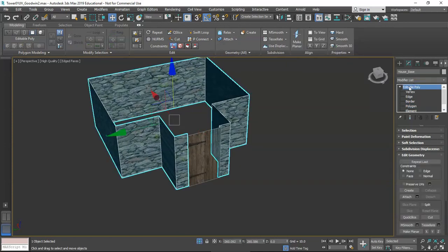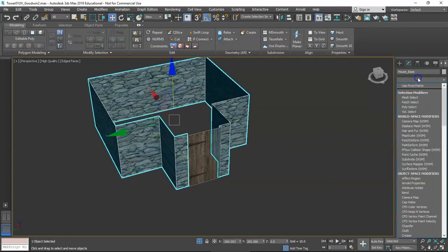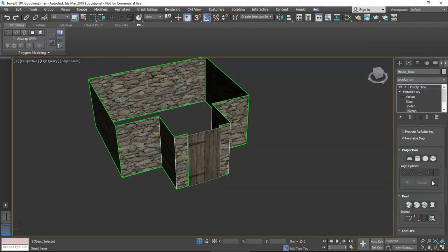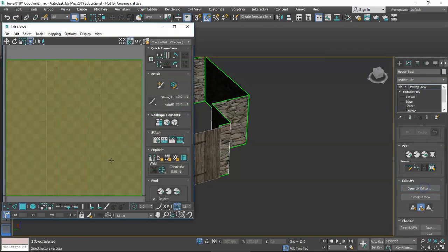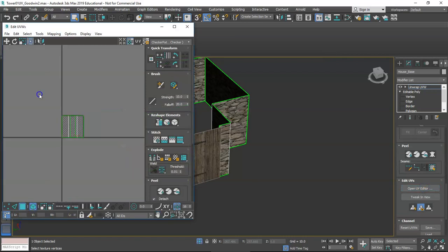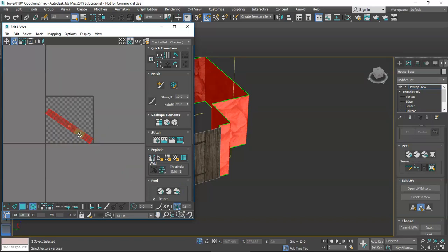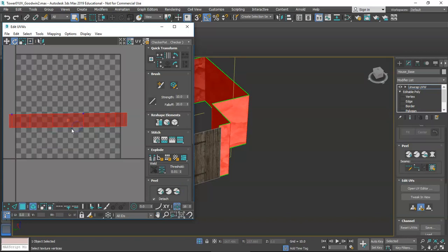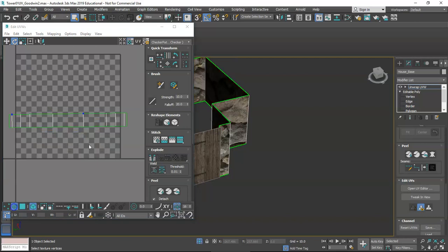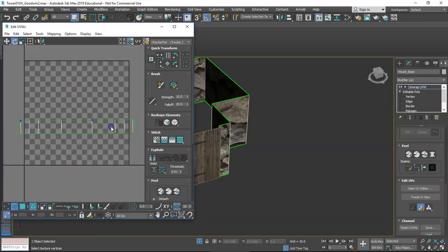So now I can just go to Edit Poly, then put the unwrap on it, open UV Editor, and I'm just going to select everything and do Reset Peel. And then rotate that. Yeah, I always hate that, but we'll just drag select, whoops, turn off element mode.